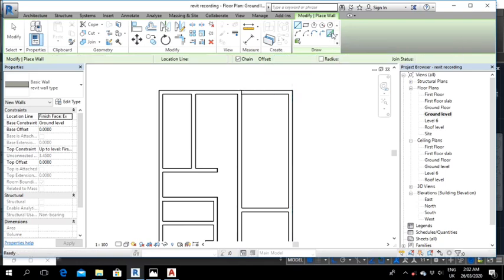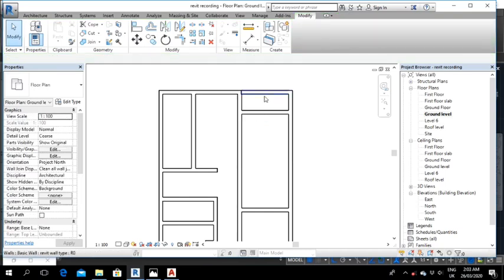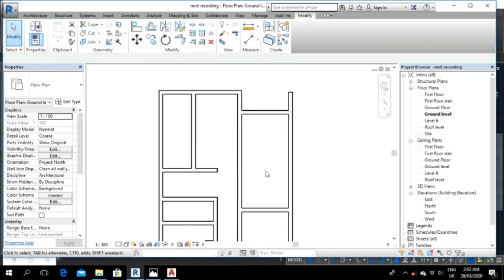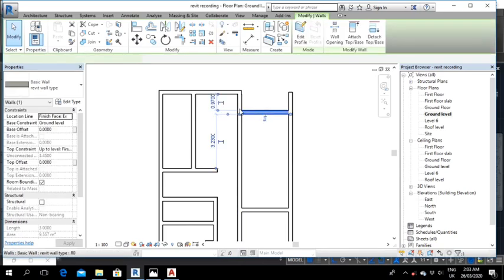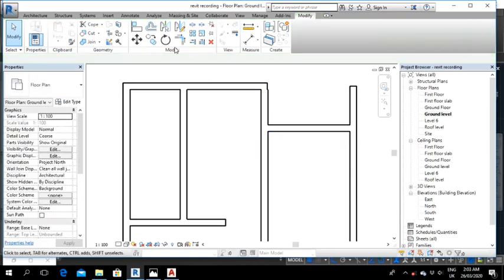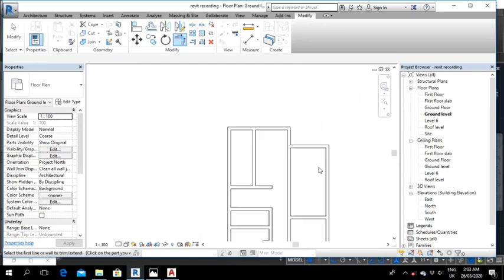Okay, then select this pick line. So when I hover on this a little, I'll find and I'll take it. Okay, escape a couple of times, then right click and delete this. Okay, the next thing is to make sure that this is 1.2 meters. So 1.2, enter. Okay, now I can use trim to make it exactly like this.